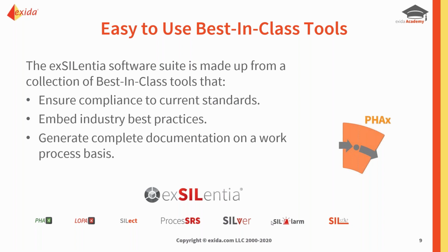The SIL alarm tool allows us to create a master alarm database. So if we've got any alarms that we are going to use as protection layers that come out of the PHA and LOPA, they can be built into the SIL alarm tool to start creating the master alarm database. If you're looking at doing rationalization, right now the SIL alarm tool can directly import and export to and from the DeltaV or from the Rockwell PlantPAx.